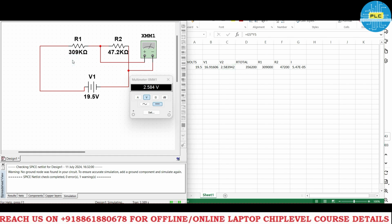Like this, the voltage divider will work. Now you got my point, right? So that's the reason R2 always should be lesser than R1, because the charging IC requires a minimum voltage. It means 2.5 to 3.3 volts or a little bit here and there. So that's the reason we calculate and they put the voltage divider resistance values.